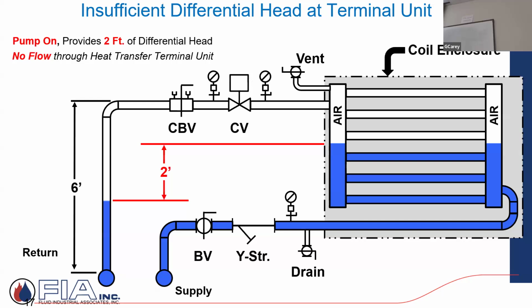So this is a little different, but that's not uncommon because, oh, I want to keep the pressure drop low and all of that. Well, that might work against us. So one of the reasons, in addition to that control valve authority we kind of touched on, is we can use it to self-purge the terminal units by making sure of the pressure drop. And it's a function of how big is that terminal unit, that air handler, that coil.